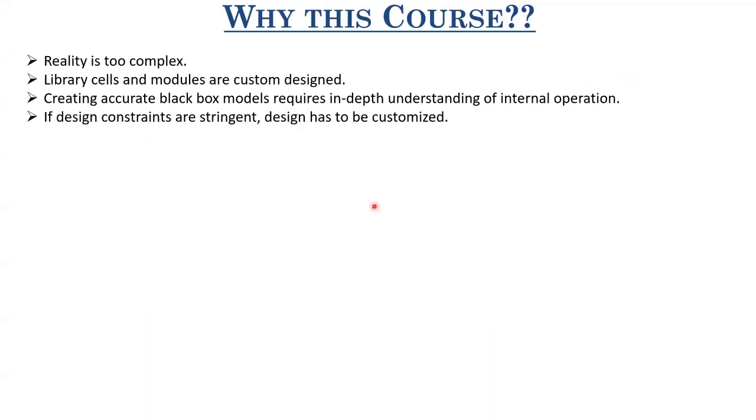Also, if the design constraints are pretty stringent, and this is the case for most of the modern designs, where we have application specific specifications from the consumer end, that makes the designs pretty stringent, and then we have to involve some level of customization. So those automated tools for semi-custom design sometimes do not even give you the correct output, or they are not able to synthesize or design circuits so as to satisfy all the constraints that are given by the consumers.